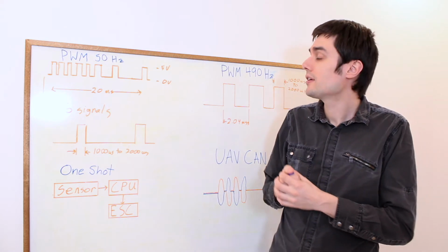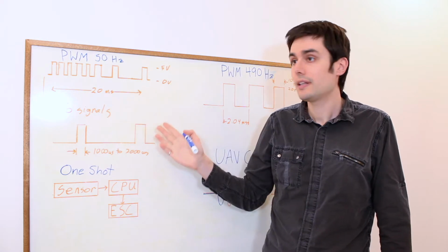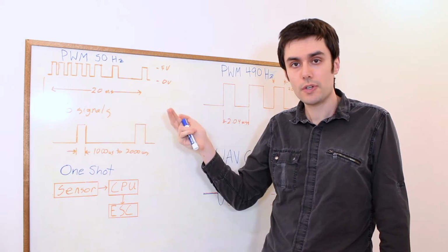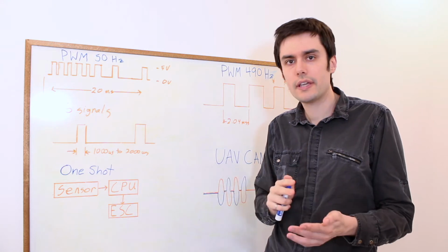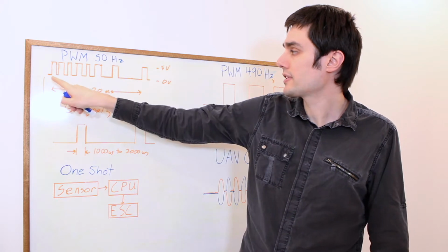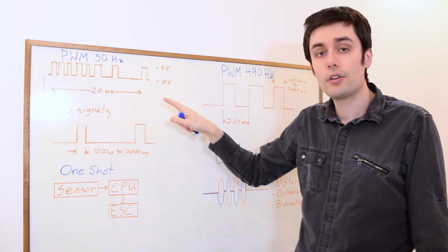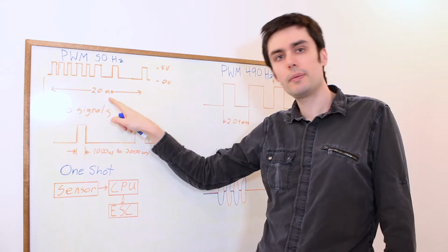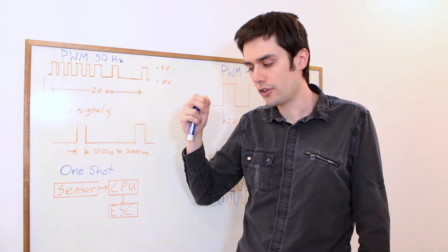So the legacy signal that's always been used is a PWM at 50 Hz. Originally, that signal was intended to be transmitted over an analog wireless transmission, and you had typically control of between 6 and 8 servos. So in a single signal here, you had, for example, servo 1, 2, 3, 4, 5, 6, and 7. And the standard in that protocol was that every update happened every 20 milliseconds, and the length of each pulse determined the control signal.